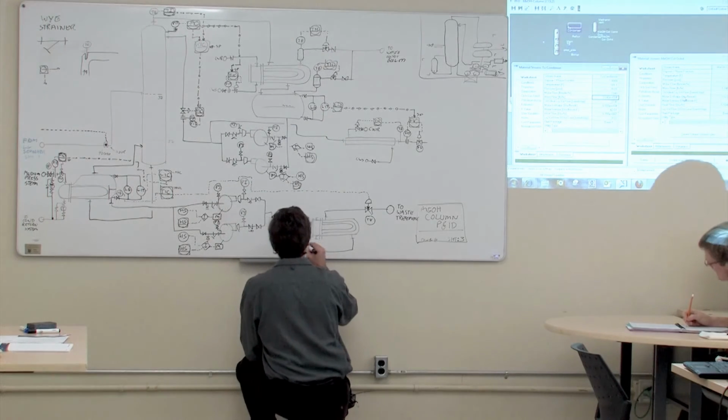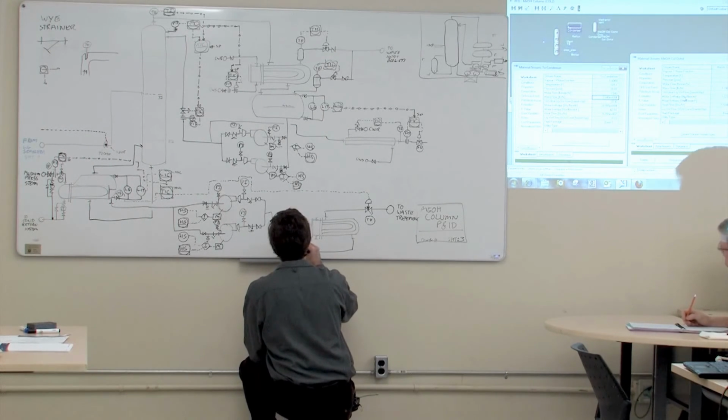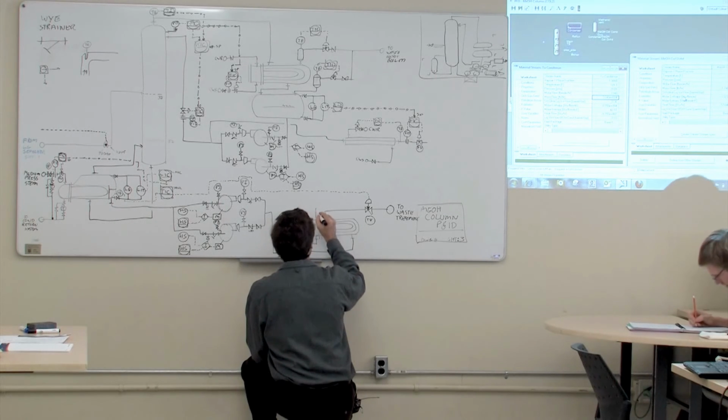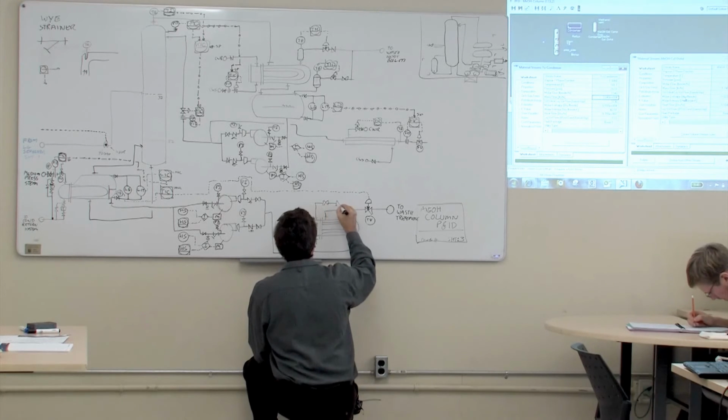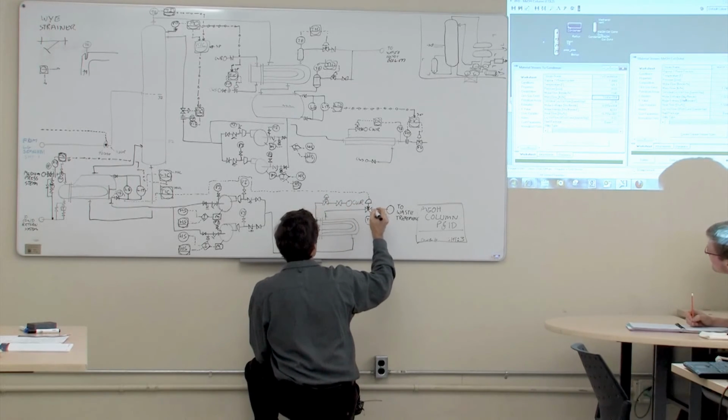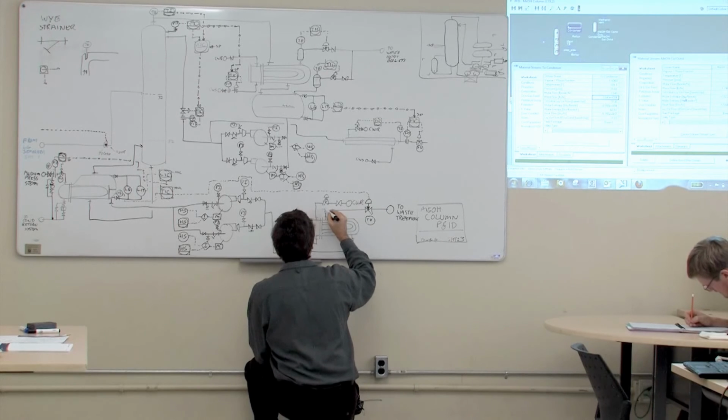So this one's going to go fast, hopefully. Cooling water supply here, manual valve. Crank that open, and I need a temperature element here.